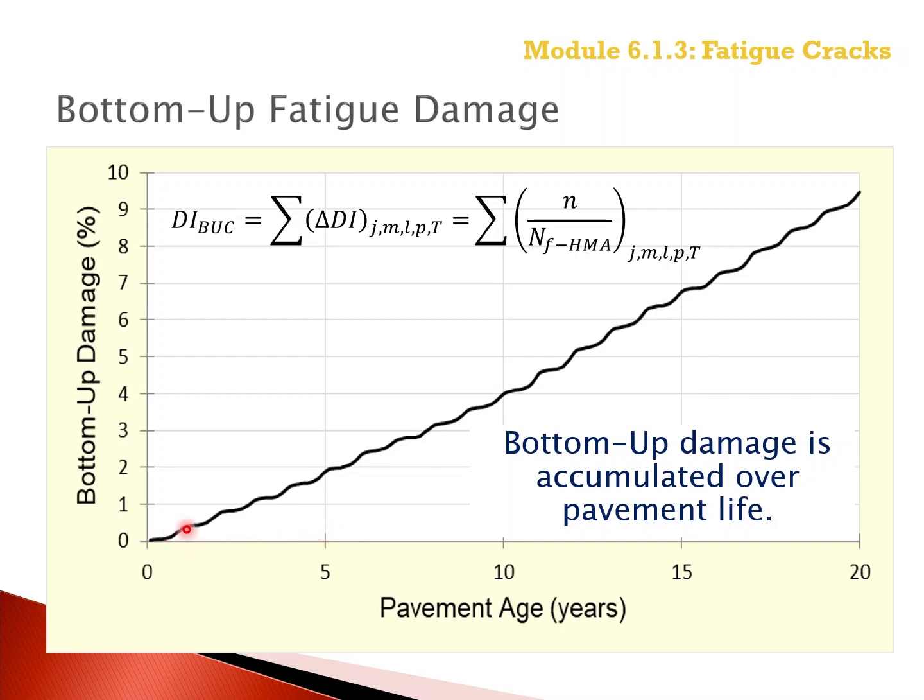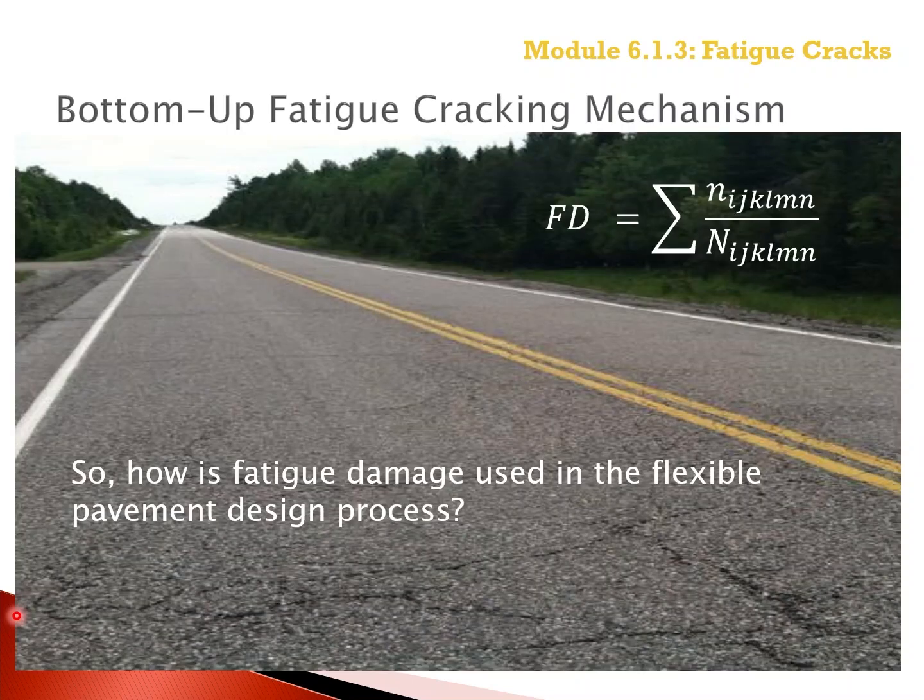So the program, when included in the output report, provides the bottom-up damage that's calculated throughout the design period. So the user can review the amount of bottom-up damage at any point in time. The PMED design software calculates the maximum accumulated fatigue damage over time using Miner's hypothesis, or the fatigue damage concept, as was explained in the previous slides.